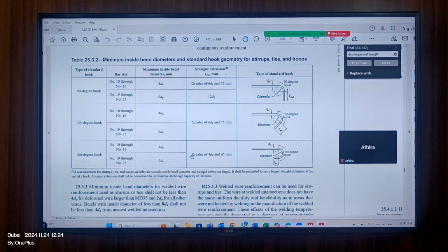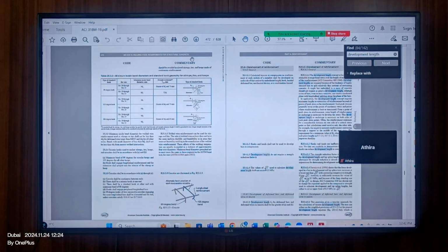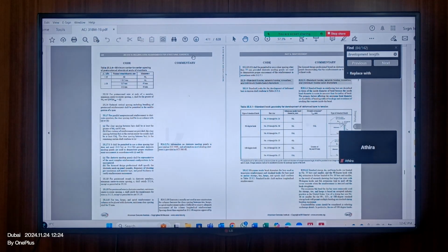If you're using the straight development length, okay, still if you want to bend it 200, 300 millimeters, the extra, I'm talking about in terms of foundation, for example. This 300 or 400 is a standard of 12 times the diameter of the rebar. The one which you are talking about, the minimum 300, 250, is not standard. The standard is this L extension, which is 12 times the diameter. Now people are rounding up the figure. If it comes to 225, they will make it 300 millimeters. That's the extension. If you want me to say it more clearly, I'll show you this 12 times diameter as well. Here, can you see it?